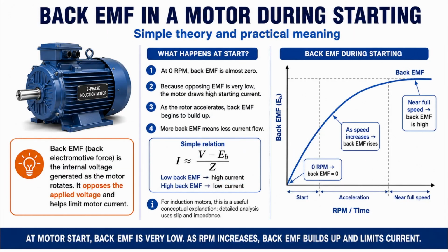Now let's follow the motor starting process step by step. When we press the start button, the contactor closes and supply voltage is applied to the motor. At that moment, the rotor is still at 0 RPM, so the motor draws a very high starting current.